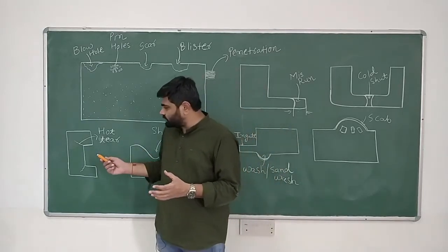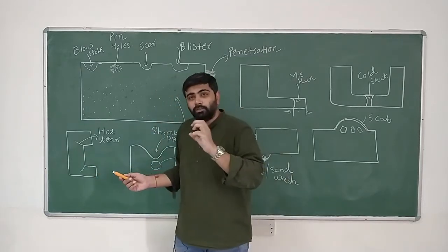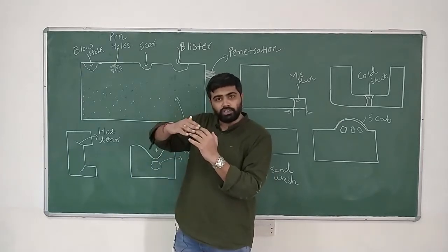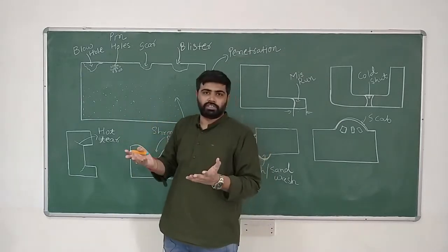So there is a certain section of a casting where the cooling is taking place very fast. There is a certain section where the cooling is taking place slowly. So due to these differential cooling rates, again, the residual stresses can form.